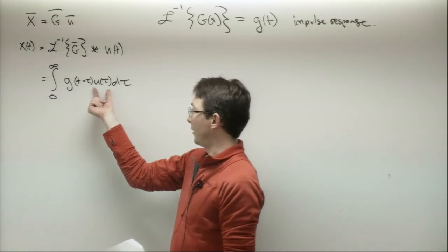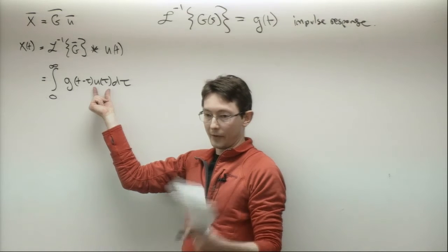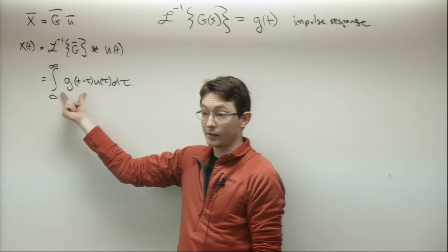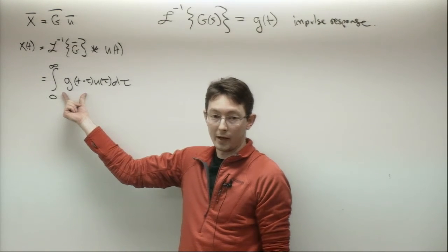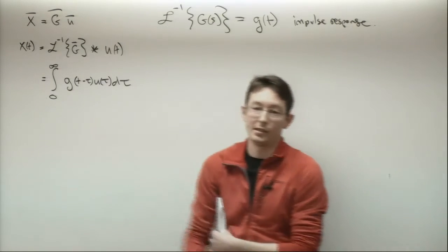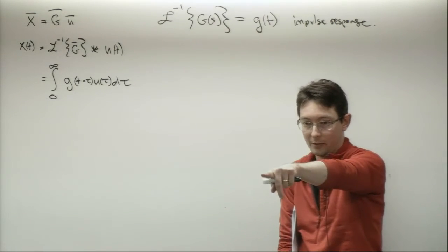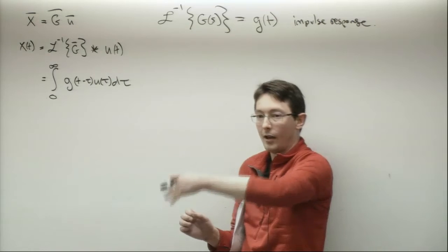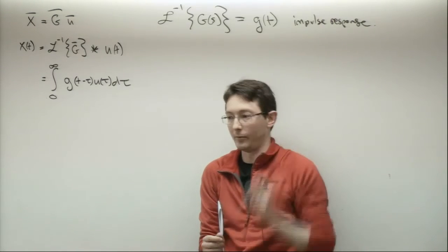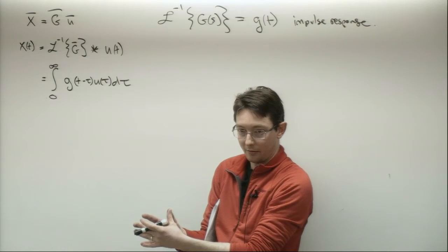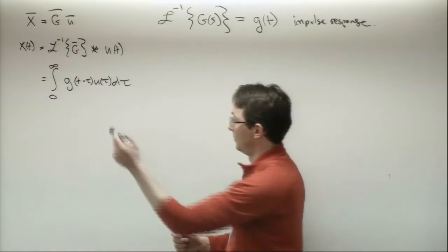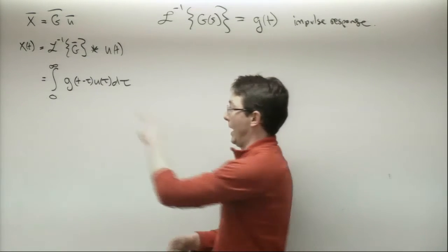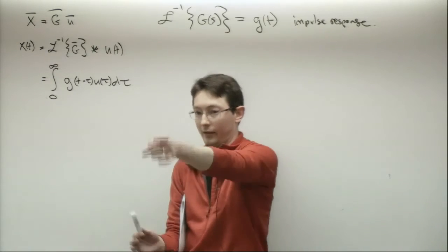So you can take that sound, u of t, which is what you sound like saying something, and then you can take the impulse response of a sound in a concert hall or underwater, or in a long hallway, or in a pool. And for this impulse response, I could just put a microphone back where one of you is sitting, detonate a small explosion right here, blast a shotgun or something, and record what you hear in your microphone position. I excite a really big initial sound, and then you record it. And you take that signal and you convolve it with any other signal you want, and what you'll get is how that thing would sound as if it was being played here and listened to there.